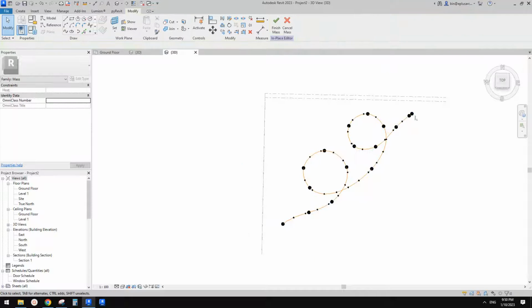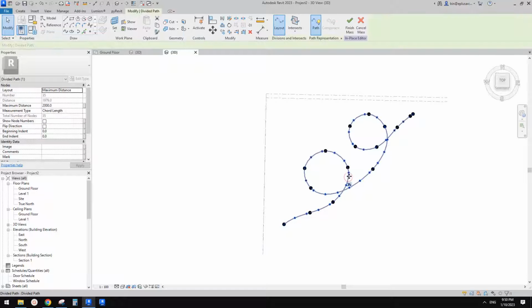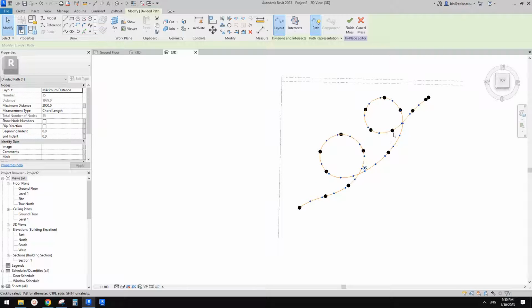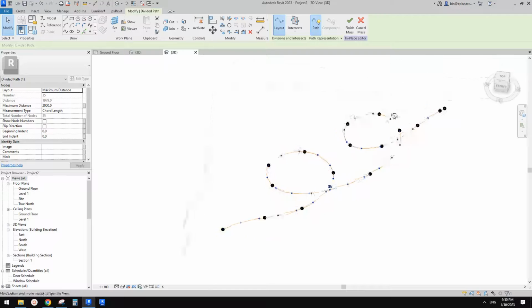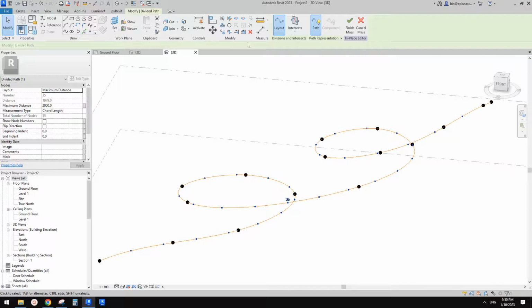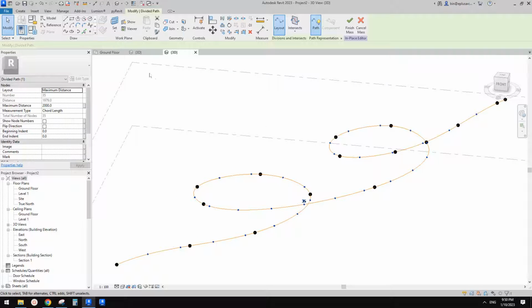So when you start to draw this shape, just check the dimension first, because spline through points, it's not spline. If you use spline, you can scale it, overall scale, and keep the size. But for spline through points, you can't do that. Okay, so I think that's for this exercise. I'll keep this overall size.